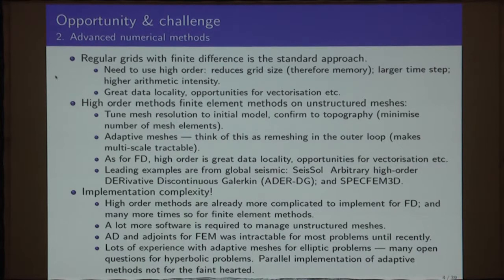And the other point then, why would you go, well, still a valid question, why would you bother at all with it? Is there anything else? Well, the other thing, of course, is that if you've got an unstructured mesh, there could be scope for efficiencies there. If there's parts of your domain that are not very interesting or homogeneous, you can use very large elements. If there's other places that are rapidly changing that have got a lot of detail, you have small elements. So if you like, you're trying to be frugal about your use of degrees of freedom in your system.